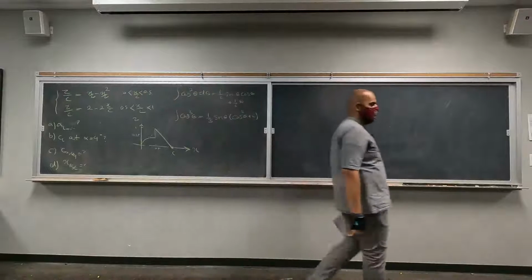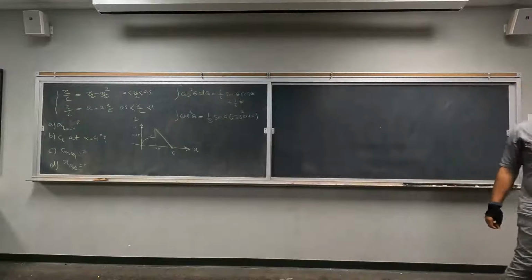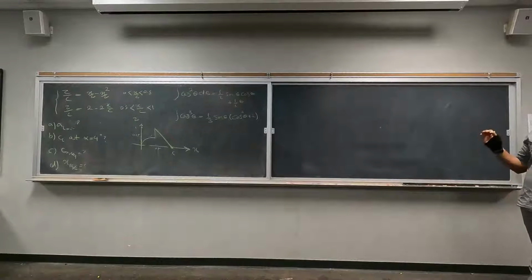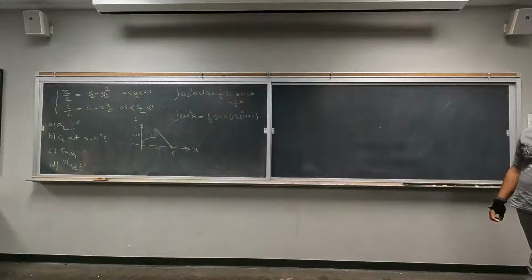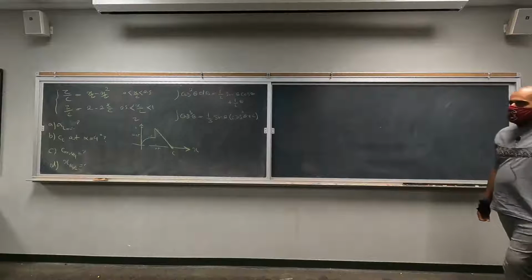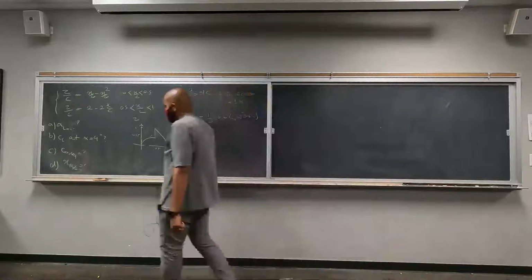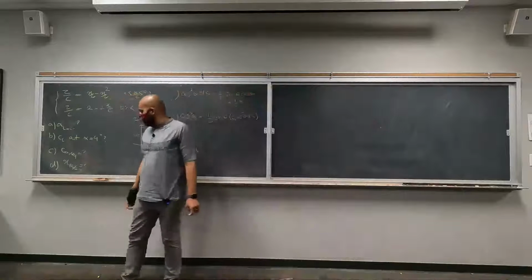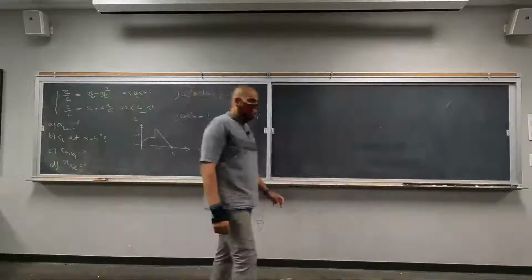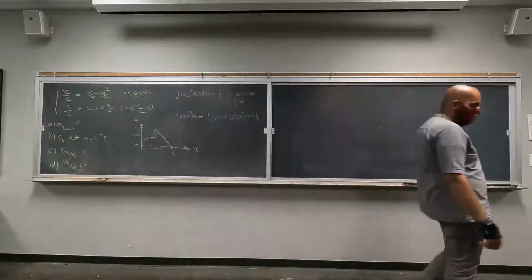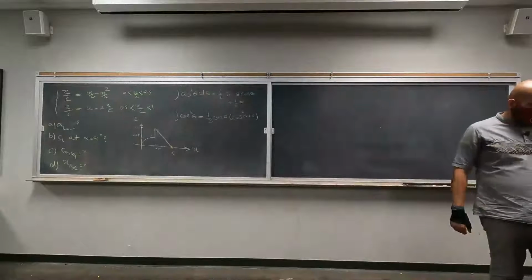But yeah, we are looking for the zero lift angle of attack. We are looking for the lift coefficient at 4 degrees. We are looking at the moment coefficient around the quarter chord. And we are also looking at the location of the center of pressure divided by c, divided by chord length. Right. You have all of the equations for it from the previous lecture.